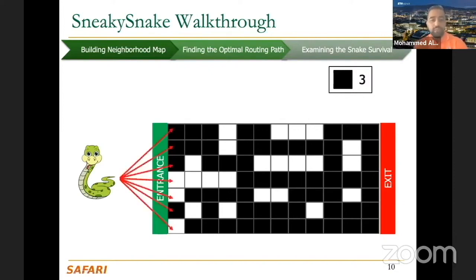So how do we solve it? It's very similar to the single net routing problem. In each row, you detect how many steps you can go further. So you find 0 steps here because you start with an obstacle or a module, so you cannot pass. Here you can move 4 steps forward, because your goal is always to go from left to right, so you want to go as far as possible in each row. That is a greedy choice to get the shortest path. Because if there are no obstacles at all, you just walk in a single row and that's it.